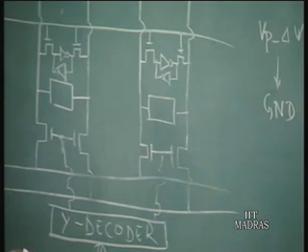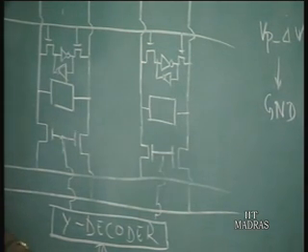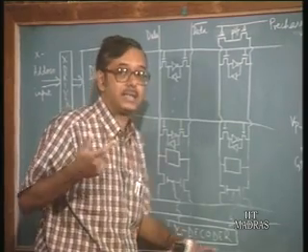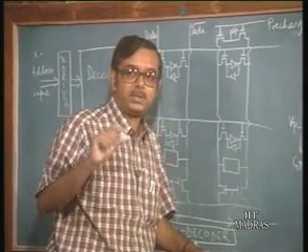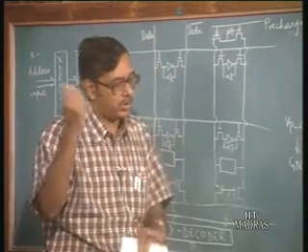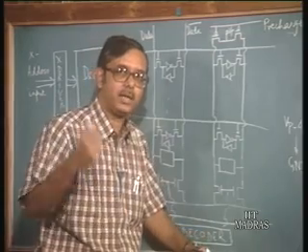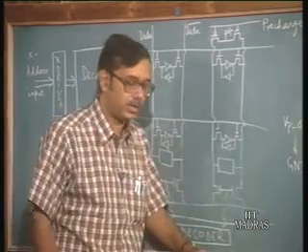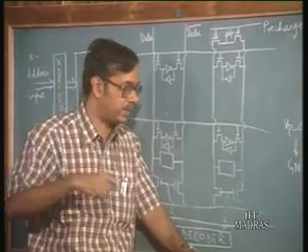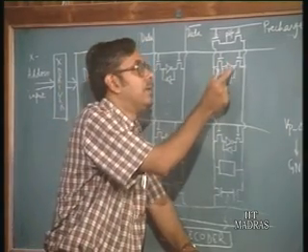It is important that the sense amplifier is not turned on right away, because if the sense amplifier is kept on initially, then due to some noise voltages, the sense amplifier may tend to go in one of the two directions, making the data line go to one of the two, high or low, directions.